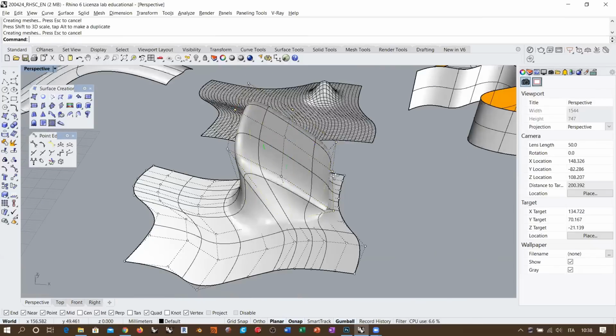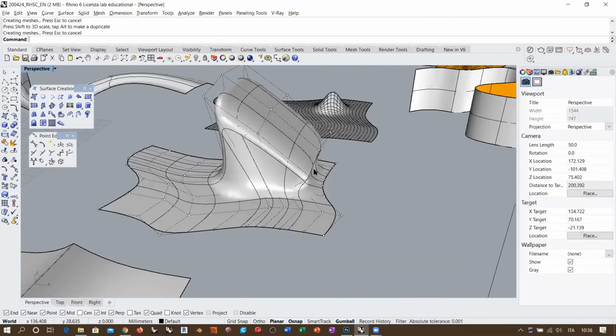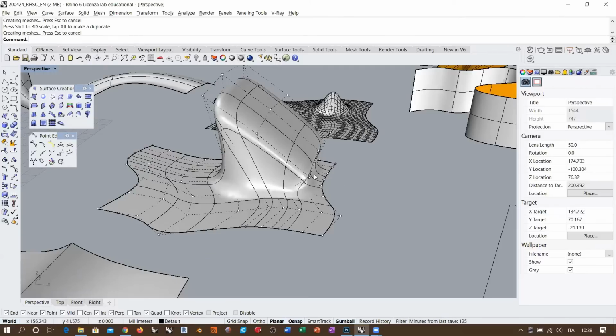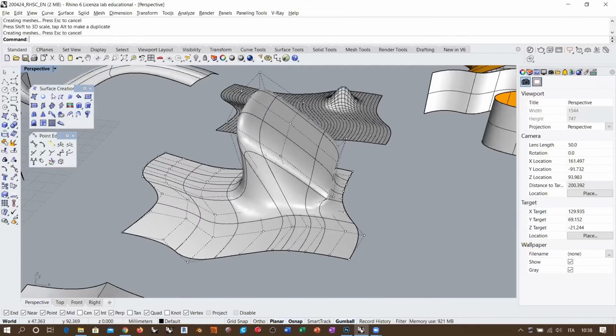Okay, so you see that also in this case, this is an extremely complex situation in terms of geometric aspect, that it's very unlikely that you can get it from any direct surface modeling tool. Okay, so once again, very simple commands like edge curved surface and topological editing in order to get the proper result. Okay, so in this case, for example, I would never work with a surface from a network of curves.